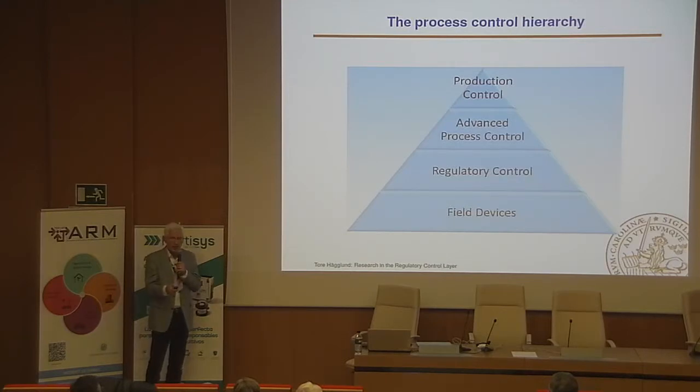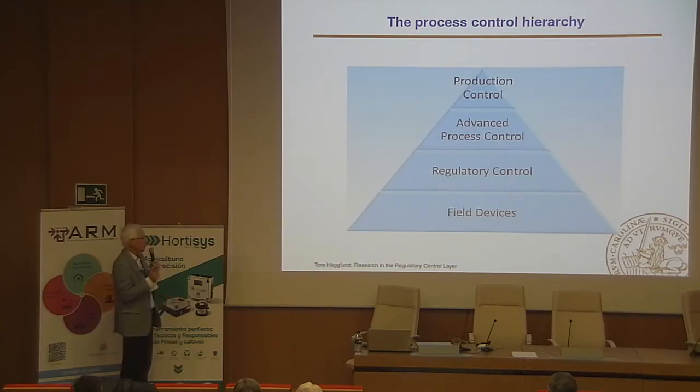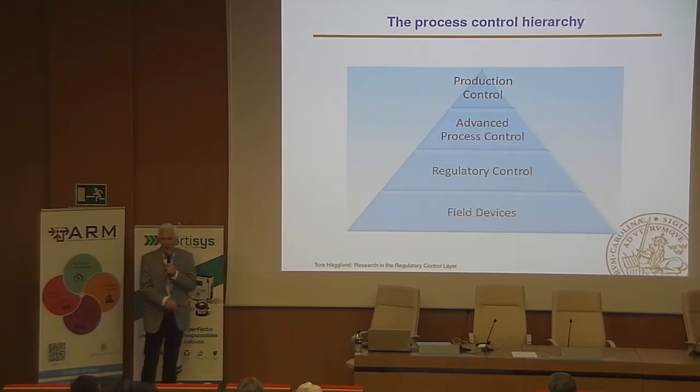After the digitalization, the academia went for these two layers. Here we have had all these advances in MPC and GPC control. But this layer was neglected, more or less, I would say. It's okay, but there is another problem, and it is that the different layers here rely on properly working lower levels. If the valve doesn't work, okay, we can try whatever we want in this layer. If the valve doesn't work, we can't do anything. So this layer must be in good shape if these layers should work properly. And if this layer should work properly, this layer must also be in good shape.